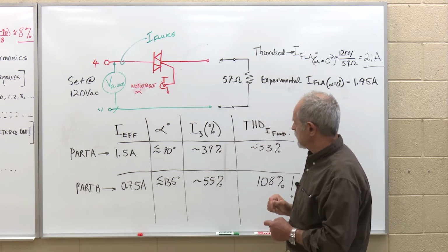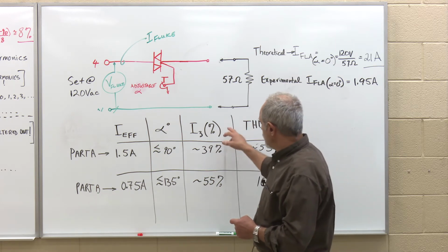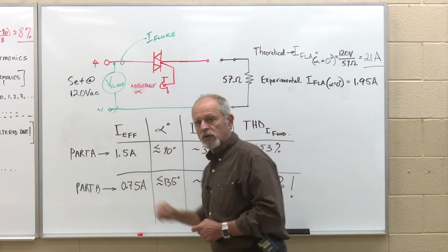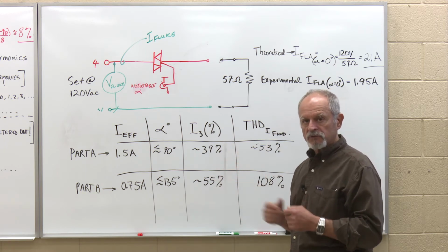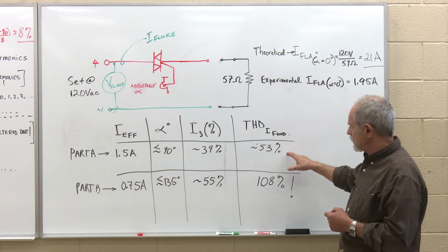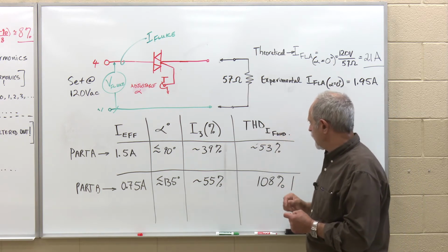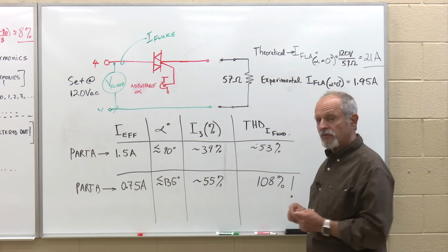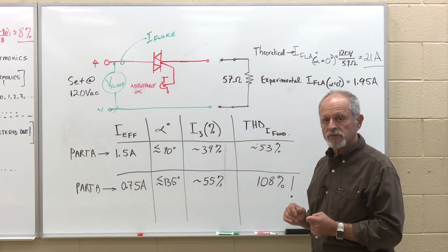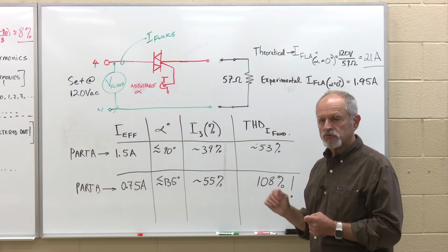We'll further see that the triplen, the third harmonic at 180 degrees, is 39% of the total effective current when we take into account the geometric sum of all the harmonics plus the fundamental. And the Fluke also tells us that based on the fundamental current, the total harmonic distortion is about 53%. So that's a fairly distorted waveform, and you'll see that when we look at the waveform on the Fluke. It looks a little bit like a chopped triangular waveform.